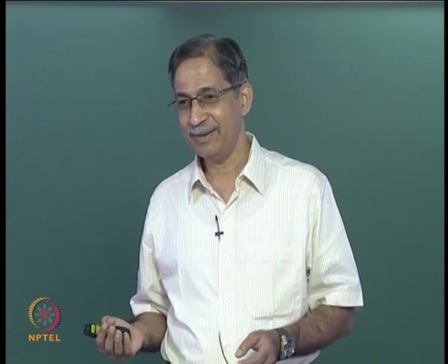We don't take advantage of it here. We don't take advantage of that hinge here, because that we will do when we ignore axial degrees of freedom. You understand? Here we are not taking advantage of the release there. I am not taking advantage in this case, but I will take your suggestion in the next case where we ignore axial deformation. So your point is valid.